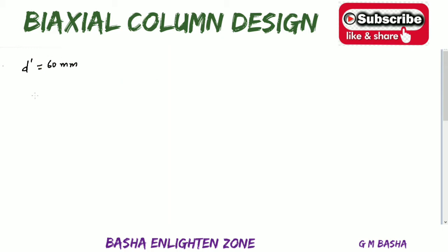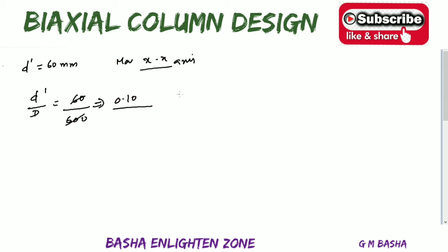Okay, then what is the d dash by d ratio? 60 by 600 along the major axis. So I am talking about the x axis. Moments are considered about the x axis. So it will cancel one zero, that is 0.10, means your d dash by d ratio will be 0.10. And we are choosing the condition of reinforcement equally on four sides, and one more condition is Fy 415 Newton per mm square.